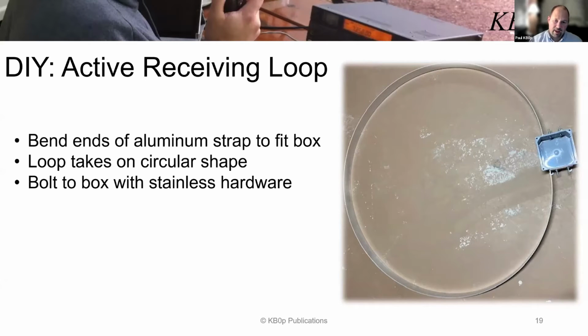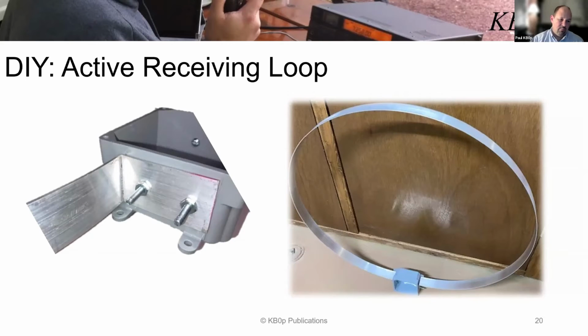So how did I fasten this straight 6 foot piece of aluminum onto this box? I did not bend this; it's just naturally bent from being mounted on this box. I measured up on each end of my aluminum strap, put it in the vise, and carefully bent it so I had a nice clean bend.